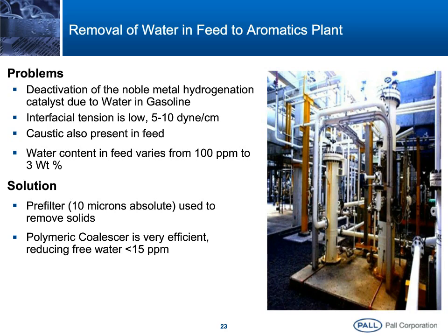And the solution here is to use a pre-filter to remove the solids, followed by a phase separator coalescer, which can withstand all of these conditions. And you can see the picture there on the right of this process. So this installation is there at about 15 plants currently around the world.